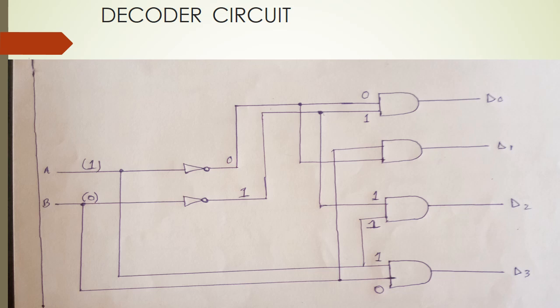So for B, let's look at the D2 terminal. Our AND gate in D2 is connected to terminal B, which is active, and the second terminal is connected to A, which is also active. So our D2 is active. At this point, we have one output, which is 1 1. Others are on and off, which is 0 and 1, 0 and 1. So D2 should be our output.